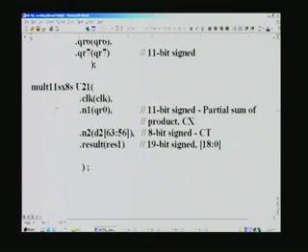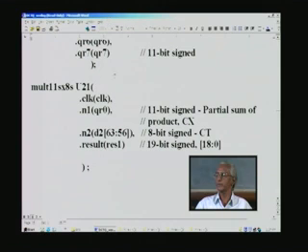In the second stage we have another set of 8 multipliers. In this case we take these partial products, which are QR0 through QR7, as one of the numbers, and the second number is the actual CT. This partial product is nothing other than Cx, and we need to multiply it with the CT matrix in order to get the final DCT. That is what we are doing here. We need 8 multipliers, and all these multipliers will be working simultaneously, concurrently.